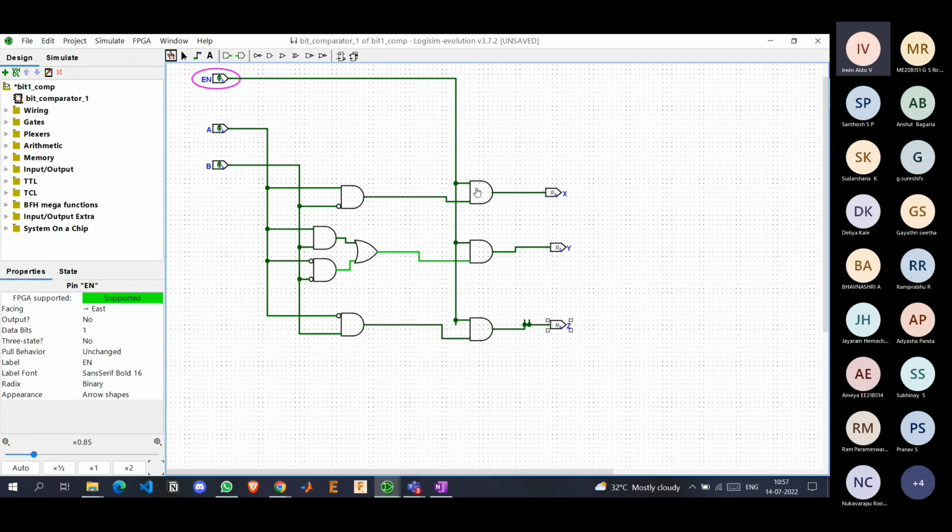In this case, for these 3 AND gates, one of the inputs is always 0. Like this input is 0, this is 0, and this is 0. What happens if one of the inputs of an AND gate is 0? The output will be definitely 0, right? Yes. So this is an off situation where every output will be 0, irrespective of what values you change.